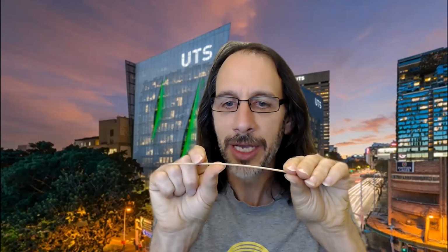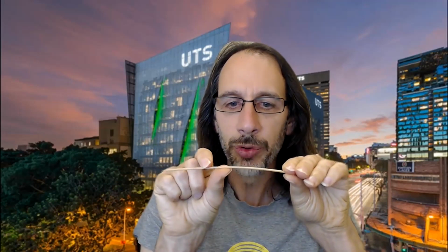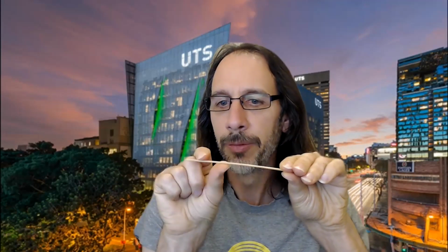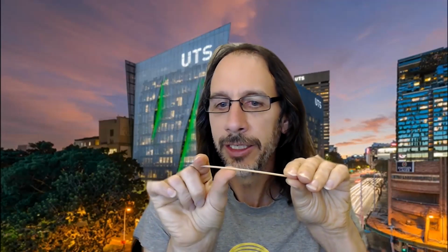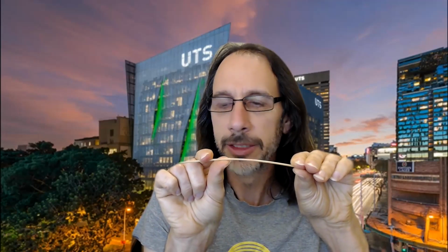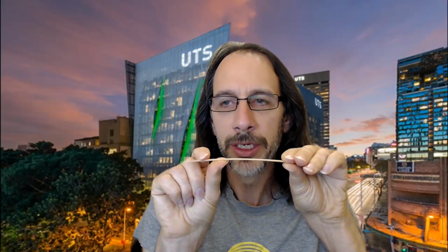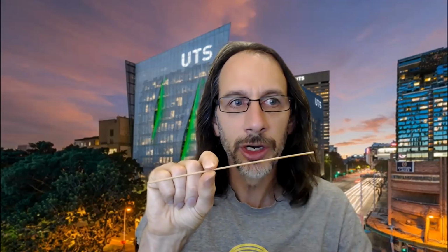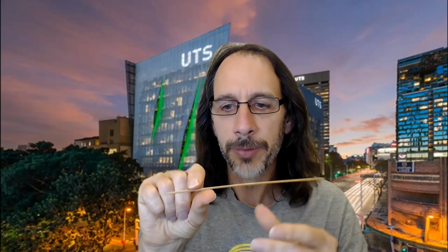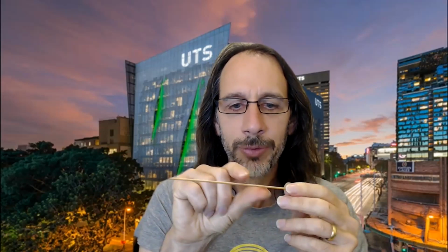But if I apply the same couple here, I get bending between my two hands, but from my right hand out to the free end here, that doesn't bend as such. There's no bending between here and here. It's just rotating as a straight line. Okay, so that's what we mean by internal and external effects. The other thing, if we're doing dynamics, whether we apply the moment like this or whether we apply the couple like this, the effect on the body in terms of how it flies off would be the same.